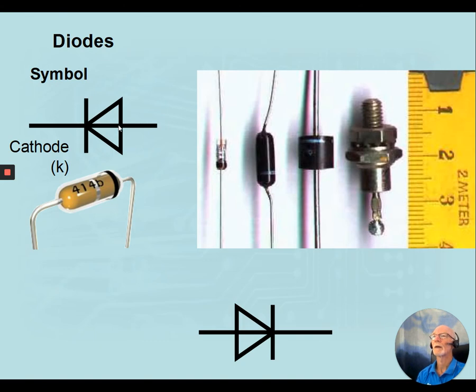The other end of our diode is the anode, and current flows in the direction of the arrow. However, this is conventional current flowing in the direction of the arrow, because diodes actually were invented before semiconductors, when we had thermionic valves. And back then it was thought that current flowed from positive to negative. So the arrow in semiconductors always points in the direction of conventional current flow.